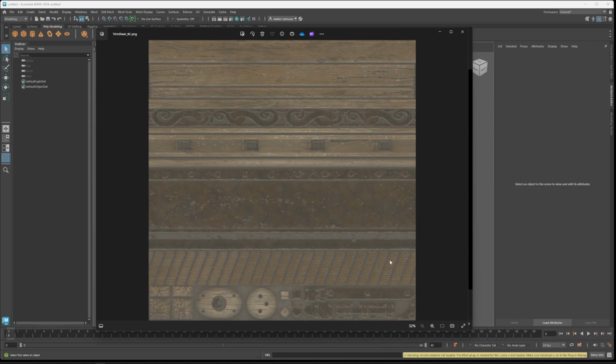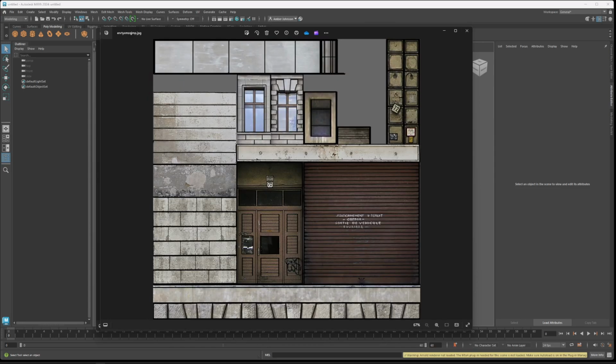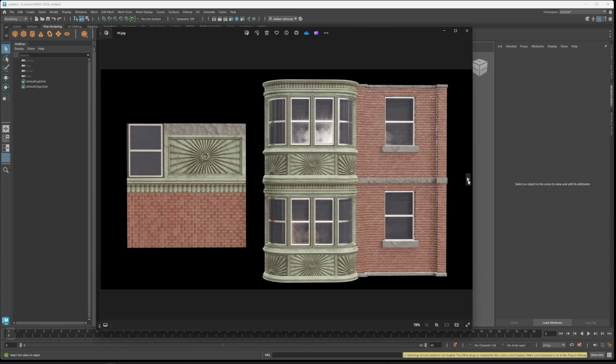What if you do have a texture that is mostly made up of these? For example, this, where it has maybe one thing that would be considered a trim, it tiles over here, but most of it is just made up of these kind of individual smaller things that do not tile at all. This is what we would refer to as a texture atlas. So a texture atlas has minimal to no tileability. Then we have our trim sheet, which has a decent amount of tileability.